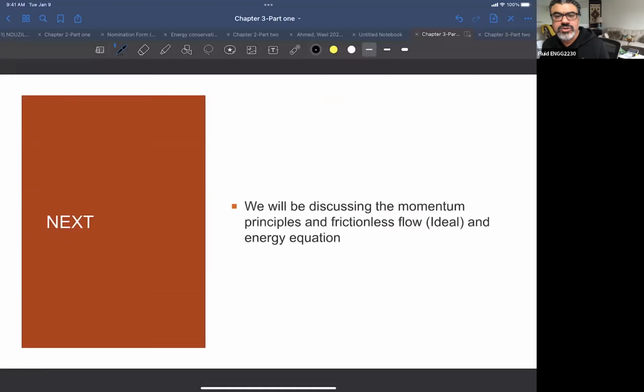I specifically mentioned that if you have MRT, that means M and R is a specific gas constant, and this is air, so it's 287. But if you have 8.3, this is universal, so you have to divide by the molecular mass, and then you multiply by 1,000, which will give you the 287.